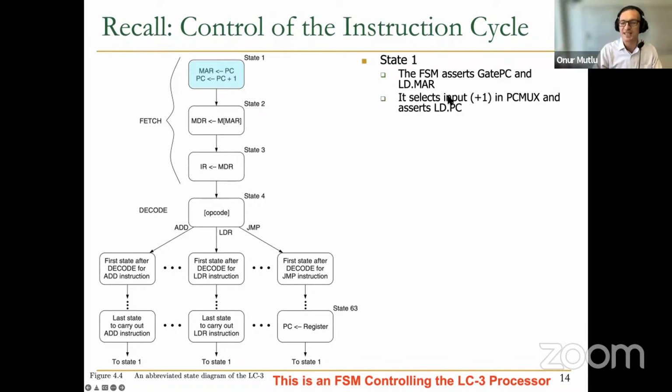So that you can get the instruction pointed to by the program counter. Also in the fetch state, PC gets incremented so that you can move on to the next instruction at the end of the execution of this instruction. Remember, this is an optimization. PC does not have to get incremented immediately, but for some other instructions, when they calculate some addresses, they require an incremented PC, as we will see in the specification of the ISA. So basically, the microarchitectural designer has some freedom as to when to increment the program counter. Keep that in mind.